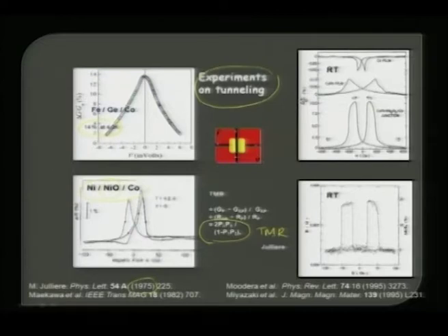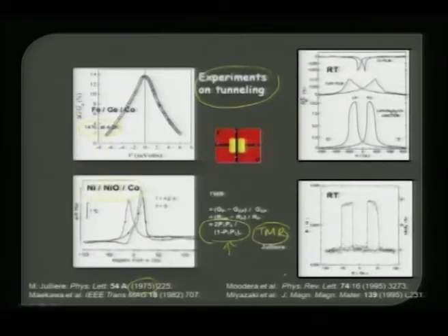So, the TMR values depend entirely on the spin polarization more than on the thickness of the metallic layers, because thickness becomes more prominent for giant magnetoresistive devices. For TMR devices it is the polarization that is more important.